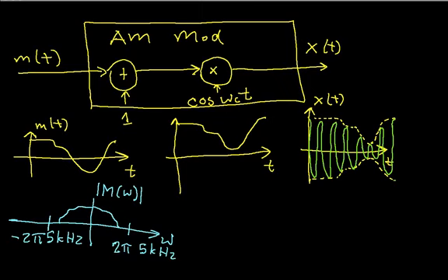And we will use this fact that it has a limited bandwidth to allow this signal plus many other radio stations that generate other signals to exist in the same frequency band. Or I'm sorry, to exist in the same electromagnetic spectrum in such a way that the radio can pick out the station you want. So this is what we have here. When we add 1, then essentially all we add is a delta function at the origin of magnitude 1. Okay, so by adding 1, I've just added this delta function. And now the magic occurs.